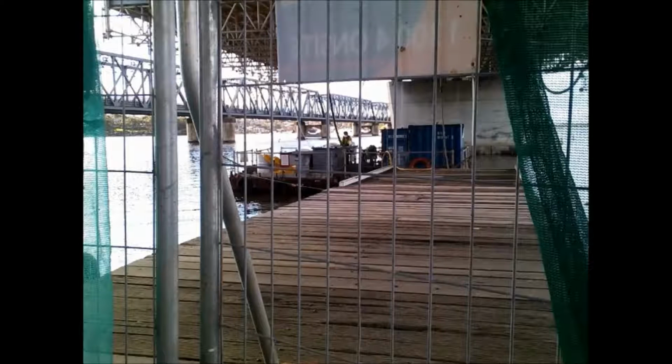The items I've mentioned so far are only to do with the air extraction to remove potential hazards out of the habitat. And in most cases, and not all, there will be a support barge set up to control the volumes of waste. There will be a person in the habitat moving the garnet to a particular spot to gravity feed it to an outlet in the habitat, and then it's transferred down to bins or drums for collection. This media may be used again, but usually not on the same project. Depending on the volumes of garnet required to perform the project, will reflect greatly in how many times those bins have to be emptied.